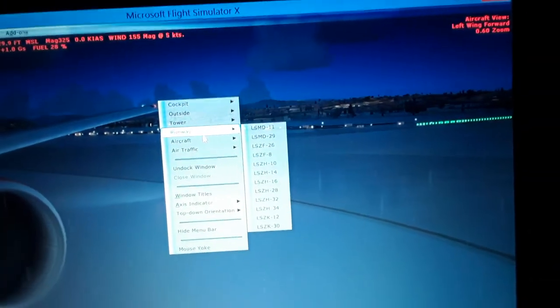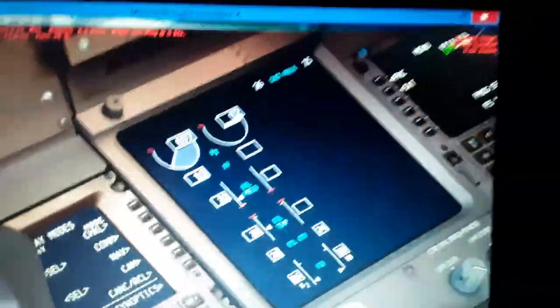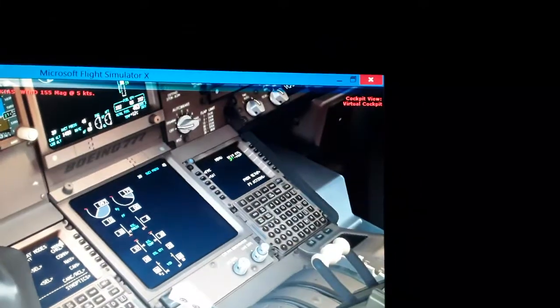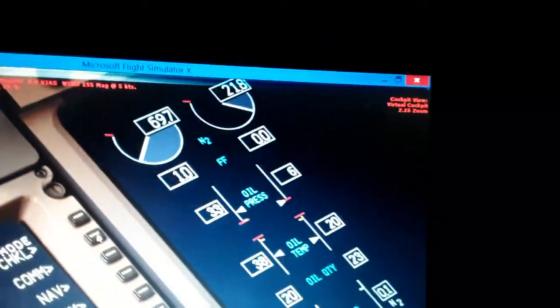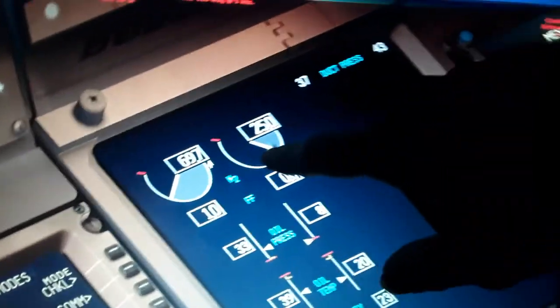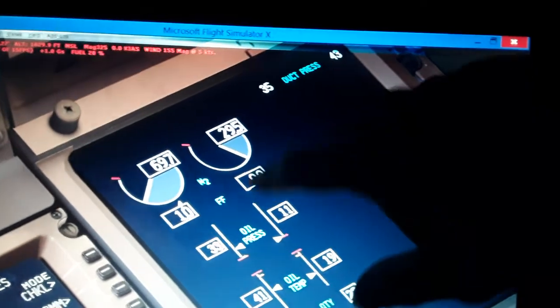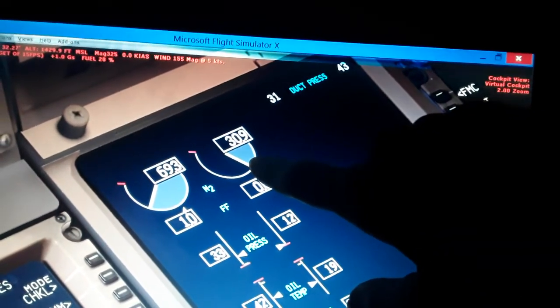So we go now to the other side engine. The right wing is off. You see no spinning. So we come here in the overhead panel, start the spinner, the right wing auto start system that controls the FADEC, the full authority digital electronic control computers that control and display the information you see here, control and monitor the engine's function, the turbofan engine's function and gearbox function. We have also the fuel flow controls and monitors the limits and the thrust levers or the auto throttle. So it's all controlled by FADEC.